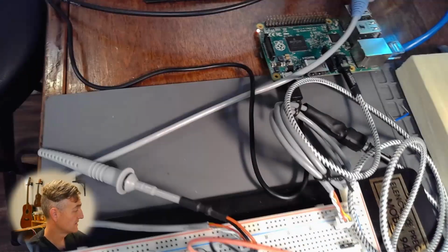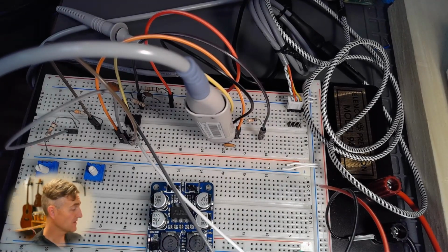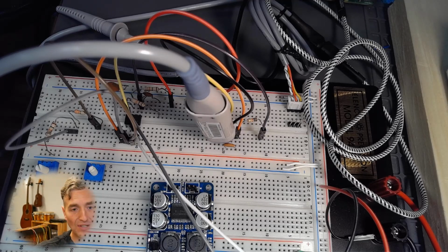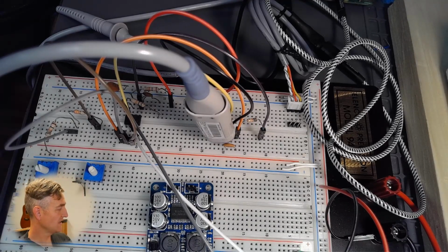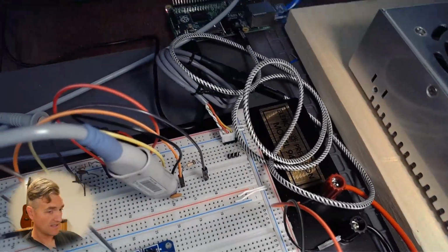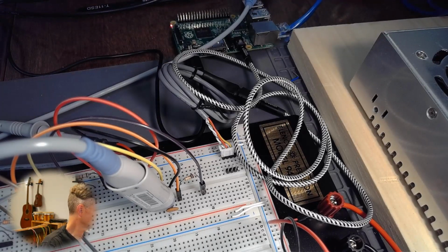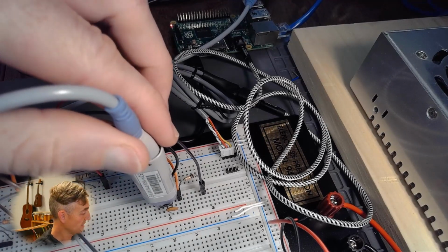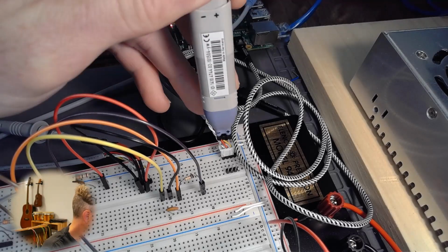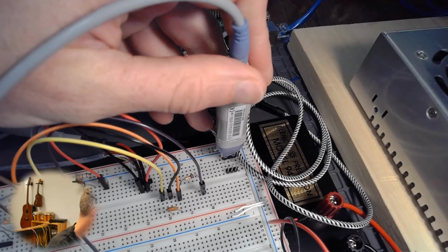First of all, since I'm using a Raspberry Pi that has a different ground than this floating ground, I don't want to shock myself. I'm going to unplug the signal, or the power from my board. So now this whole thing is turned off. And I am going to turn off the signal generator here really quickly, because I'm not going to actually use the signal generator from my oscilloscope. I'm going to use the Raspberry Pi as a signal generator. And I'm just going to look at the output of the Raspberry Pi.